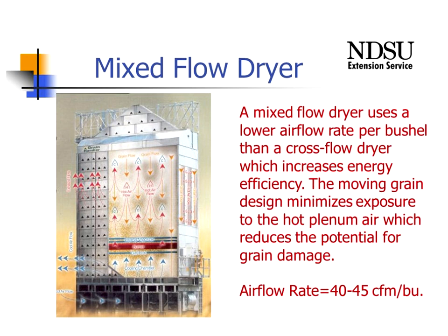This is also the dryer now that is operating at about 45 CFM per bushel of holding capacity, where the traditional cross flow is going to be closer to the 70 to 90 CFM per bushel. That makes this dryer quite energy efficient. And the common question is, is this dryer then more energy efficient than the cross flow dryer?